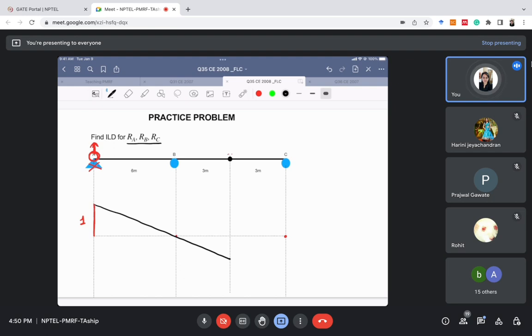Let's call it point D. At point D there was a hinge, so it can rotate here, so it can have some relative angle change. Here it cannot have any angle change. If it is theta here, it has to be theta there, but it can change angle at the hinge. Now it is supported here, so I'll join it simply like this. Okay, so it's a little complicated.